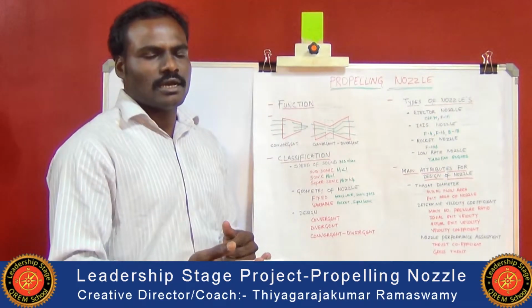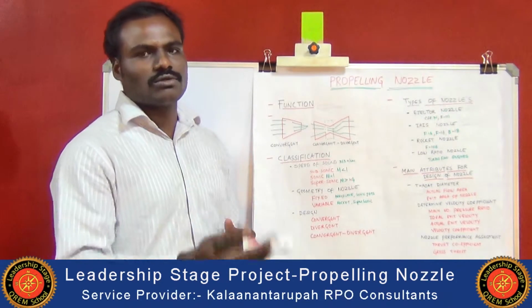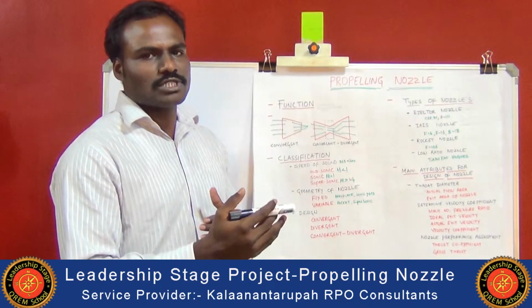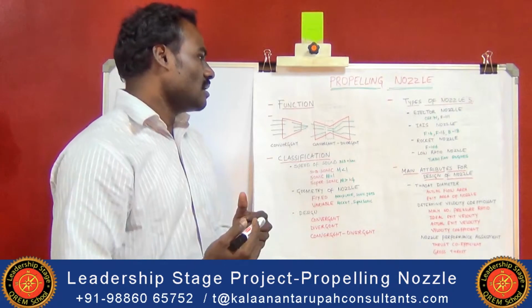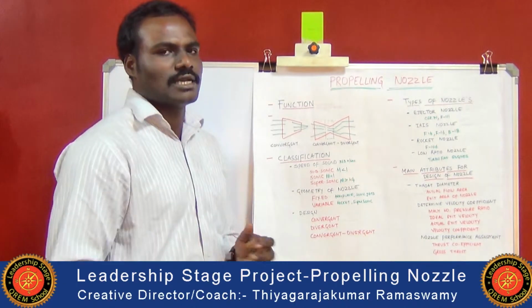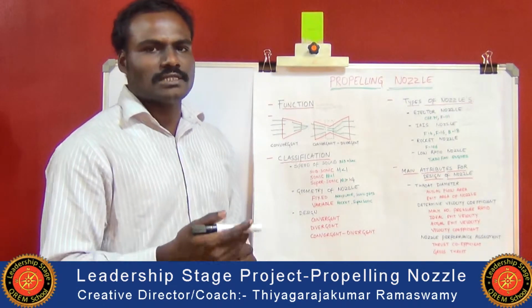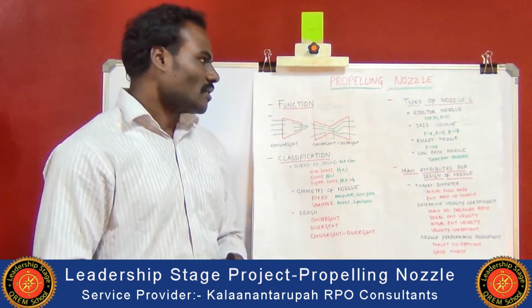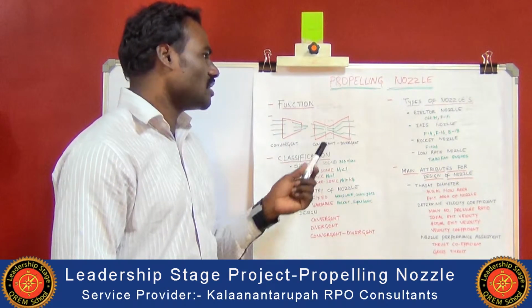The nozzle helps with back pressure control to the engine, so that the engine attains a stable position, and it also acts as an accelerating device, which helps in converting thermal energy into kinetic energy.